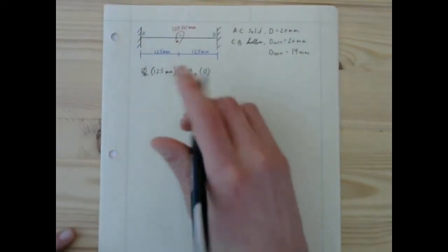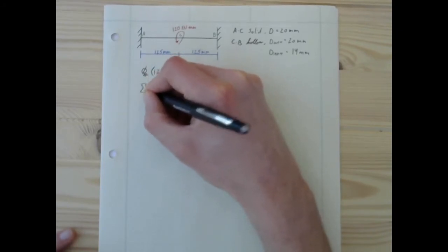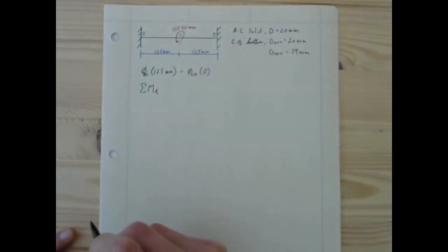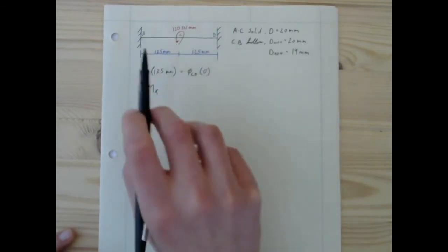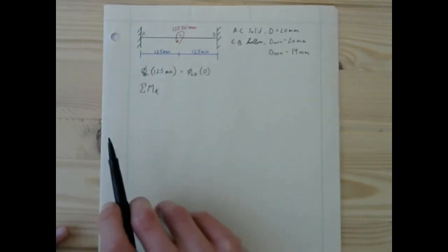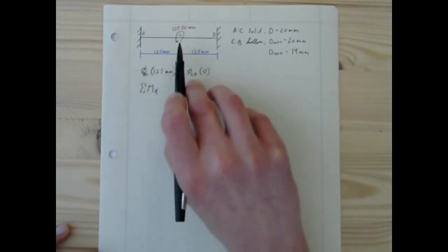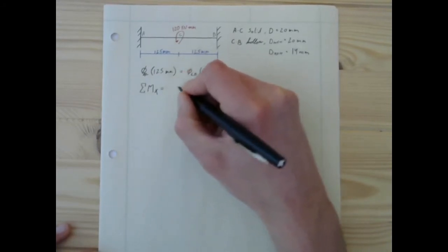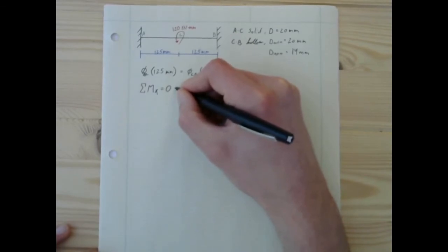And that's going to be in addition to the equation for the summation of moment about the x-axis. If this is the x-axis along here, this moment is going about there. I drew it very poorly. I should have left a little space there so that we could see which way is which. This is meant to be positive torsion. So the summation of moment about the x-axis, of course, has to be 0 for our equilibrium equation,